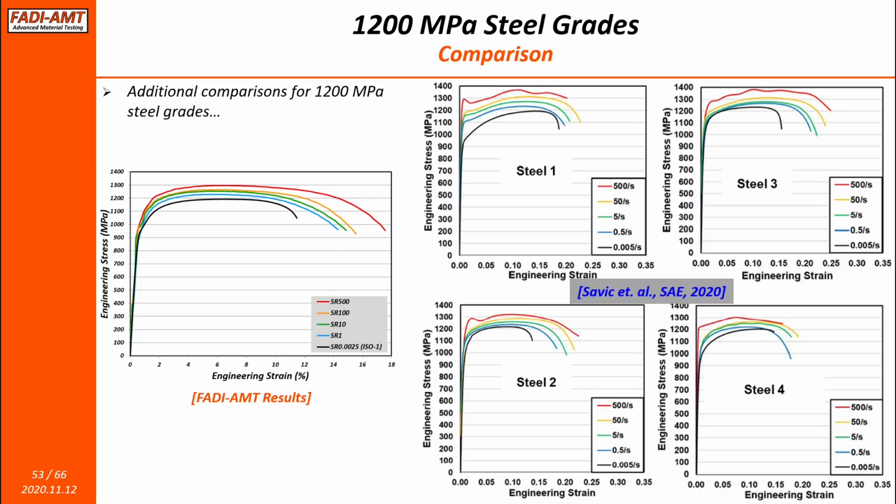Do not forget something we mentioned, and if I didn't mention it clearly, I would like to mention it again. For high-rate testing, you should avoid the elastic region. You will not get any reasonable results there because of limitations on the accuracy of your strain measurement. DIC is fantastic. It just cannot solve these problems easily.